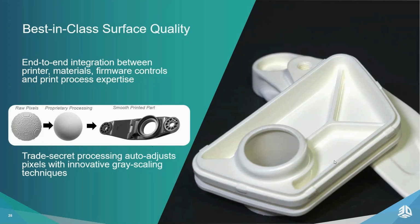So this really is one of 3D Systems' specialties. Our internally developed image processing software, we're able to automatically adjust the system's pixel edges. So I mentioned it's a 90 micron native pixel size, but we're able to deliver really, really good quality results, even with those 90 micron pixels, using our edge grayscaling techniques. And the result is extremely high quality, production grade, good looking injection mold quality parts. I don't think there's many systems out there that will deliver this quality with these material chemistries.